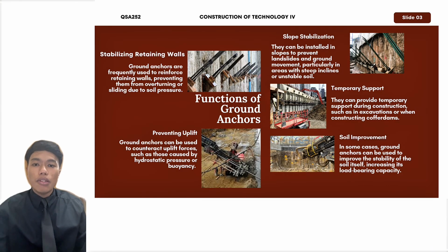For stabilizing retaining walls, ground anchors are frequently used to reinforce retaining walls, preventing them from overturning or sliding due to soil pressure. For preventing uplift, ground anchors can be used to counteract uplift force, such as those caused by hydrostatic pressure or buoyancy. For slope stabilization, they can be installed in slope to prevent landslide and ground movement, particularly in areas with steep or unstable soil.